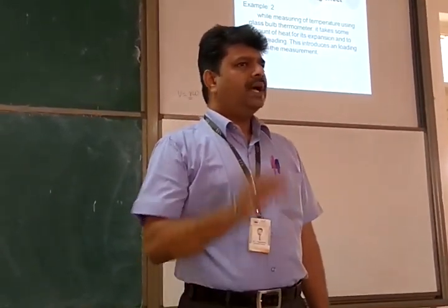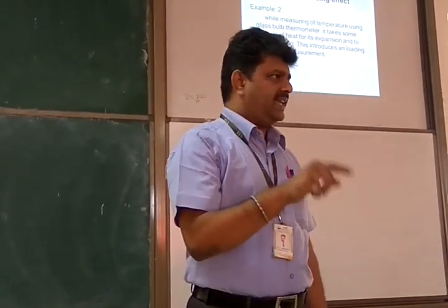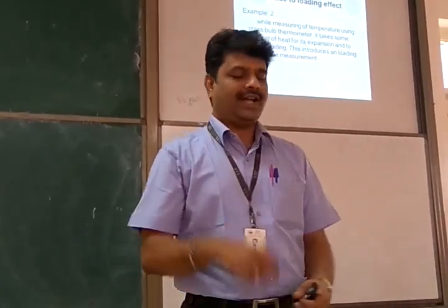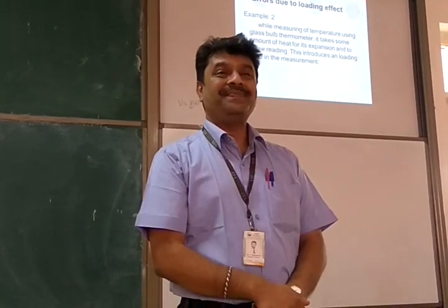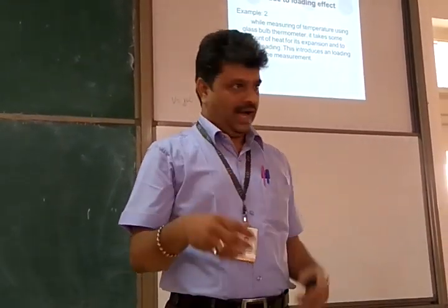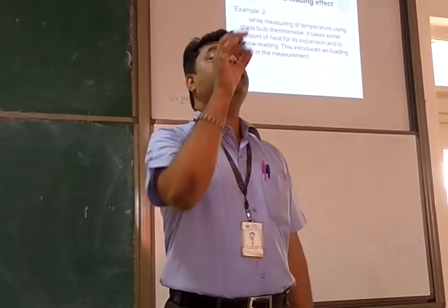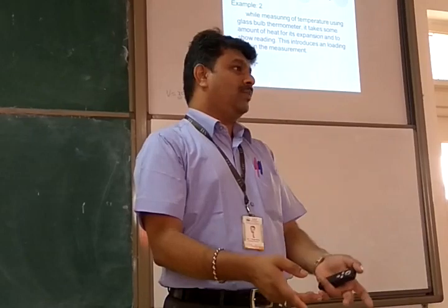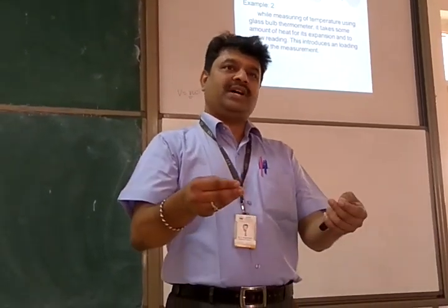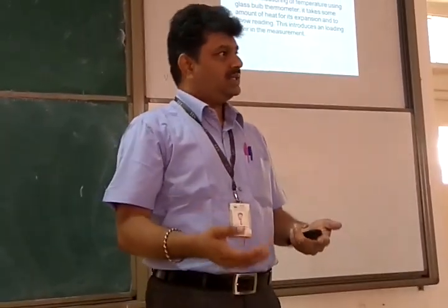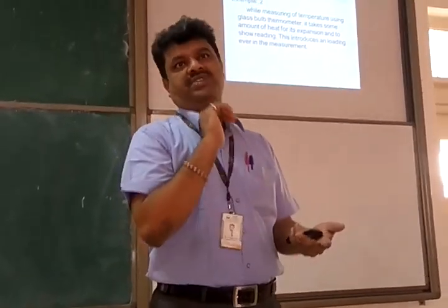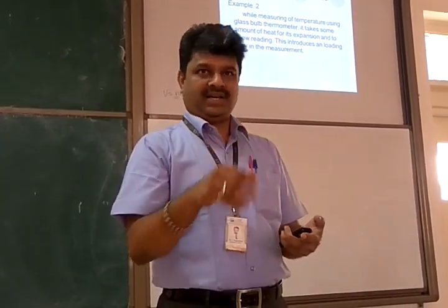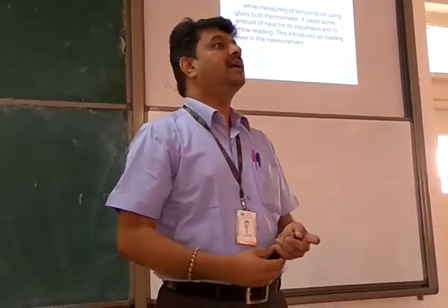Isn't it? Do you think the temperature will be the same before inserting and after inserting the thermometer? No. I wanted to measure the actual temperature. I am inserting a thermometer, and just because I inserted it, some amount of heat is absorbed and the temperature drops down. This drop in temperature, because of the thermometer which I have inserted for the purpose of measurement, is loading.